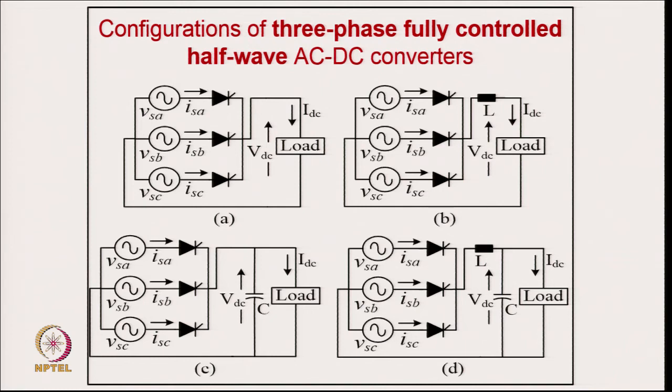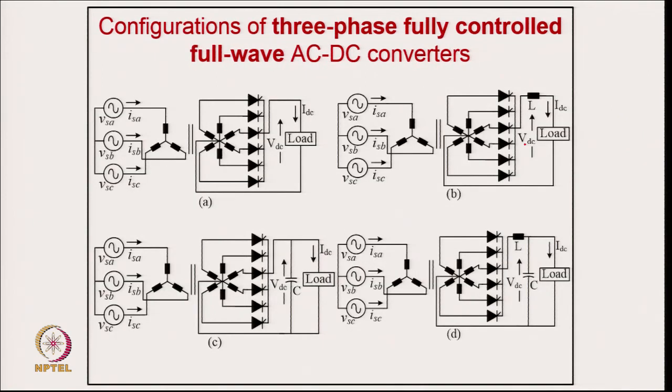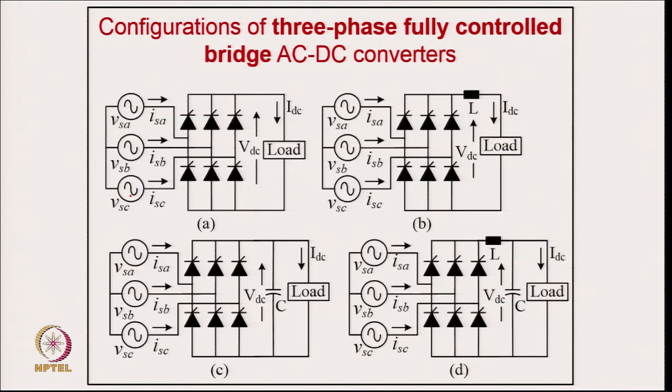Of course, the waveform may change with a filter, like an LC filter or an inductive filter. Normally, this circuit is used with an inductive filter, or the load itself has a large inductance, but they have harmonics as well as reactive power burden from the supply system. It even draws a DC component, and it is again a full wave bridge converter. You get a quasi-square current, but you can understand you get harmonics as well as reactive power burden on the supply system in all these.